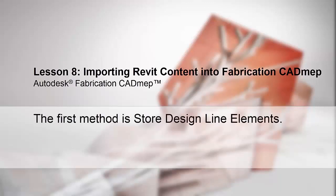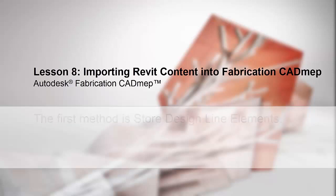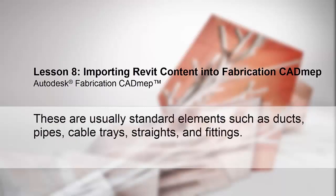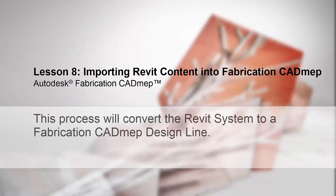The first method is Store Design Line Elements. This method should be used where Revit elements can be mapped to corresponding items in CADmep. These are usually standard elements such as ducts, pipes, cable trays, straights, and fittings. This process will convert the Revit system to a CADmep design line.